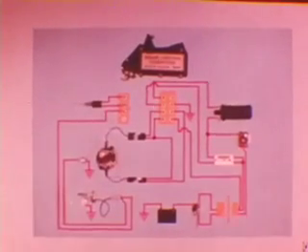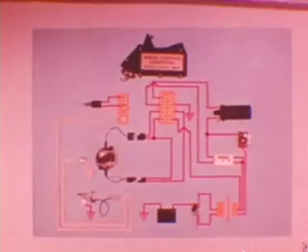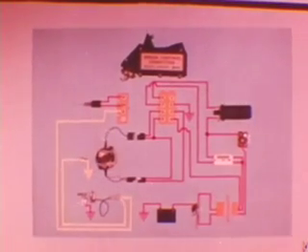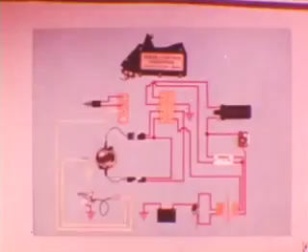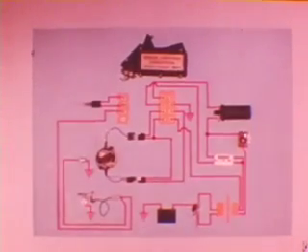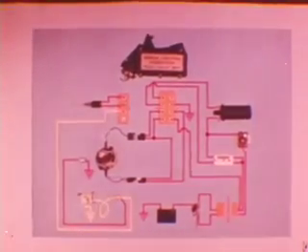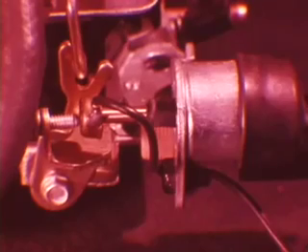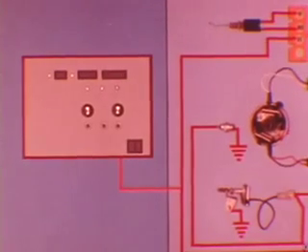You'll remember that the coolant temperature switch closes when the engine is cold and grounds out the computer vacuum transducer circuit through terminal 11. Terminal 11 is also grounded out when the carb switch closes, in the closed throttle position. For earlier cars with an idle stop solenoid, remember to turn the ignition key on to activate the solenoid. You can remember it this way.